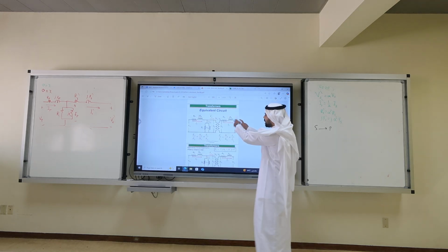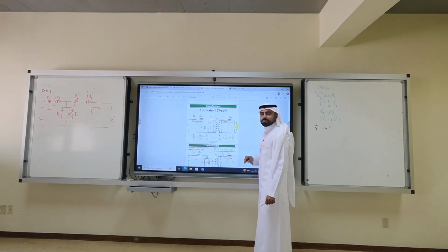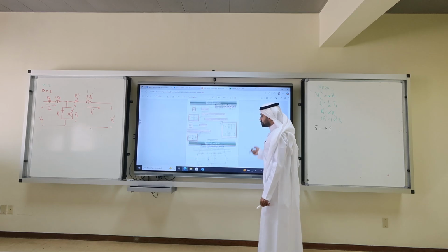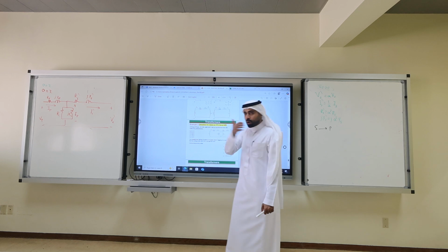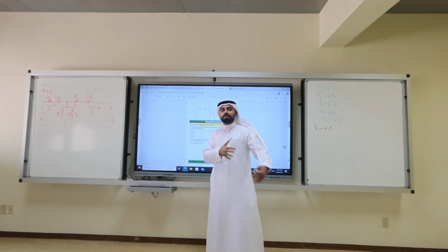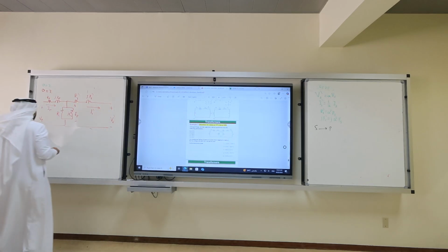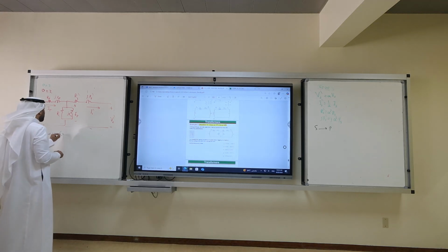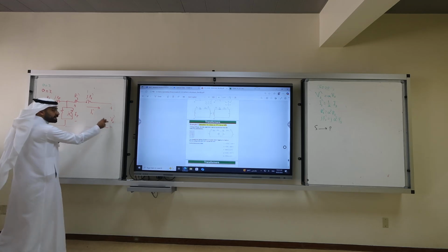So when I do calculations, I deal with Vs and Is, not Vs prime and Is prime. When I connect the load, this circuit is referred. Either I refer the load to the source, or I do a separate calculation. I prefer to use a separate calculation. So at the load side, not shown above, because this is the reflected side.